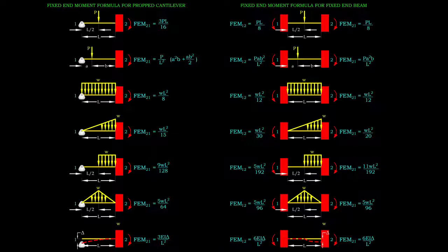In the slope-deflection equation, the unknown fixed end moment can be calculated using readily available formulas based on the support condition and loading type. Since end moments are present at both ends, we may regard all spans as fixed end beams.